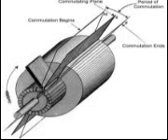The brushes are usually adjustable so that the pressure of the brushes on the commutator can be varied and the position of the brushes with respect to the segments can be adjusted. The constant making and breaking of connections to the coils in which a voltage is being induced. Figure 9-10. The 2-pole and a 4-pole frame assembly.